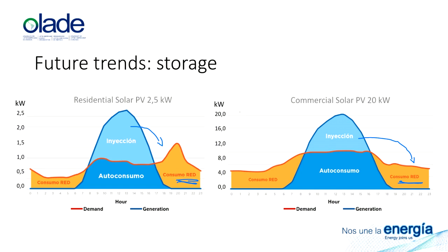And then another comment on this that we touched on when we discussed net metering and net billing. So while net metering doesn't have an incentive for storage from the user perspective, unless you provide an artificial incentive, one of the advantages of net billing is that, as you remember, the injections price is lower than the avoided cost of self-consumption.